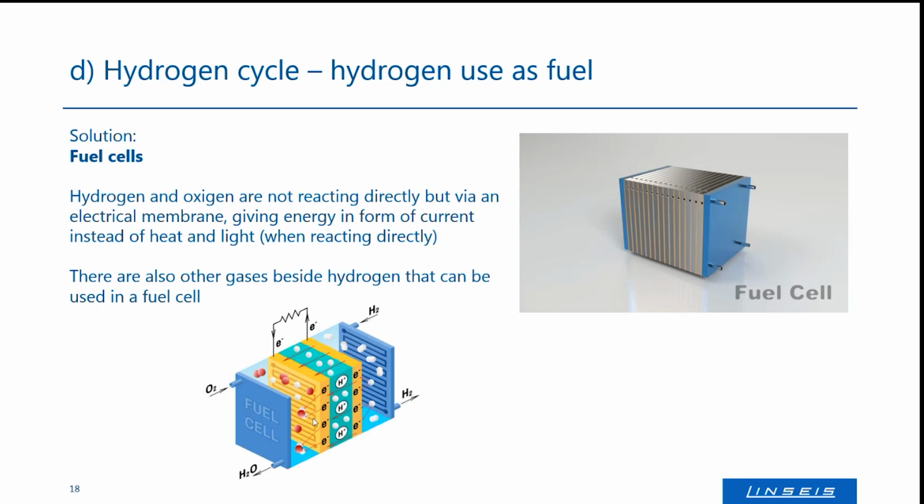By this process, the electrons that are not necessary and are released during this process can flow within this membrane in an electric circuit, and these electrons that flow into this electrical setup generate the electrical voltage that I need. So I transfer the molecules back into water molecules and electrons. That's what the fuel cell more or less does. So this process directly uses the energy out of the reaction between hydrogen and oxygen, and you cannot get it even better. So you cannot optimize this. This is almost 100% transformation rate. You directly grab the electrons out of the process without them causing heat, causing pressure, causing something. You just form water. The water drops out here, and the electrons, the energy, is directly consumed in the electric circuit. And that's what a fuel cell more or less does.